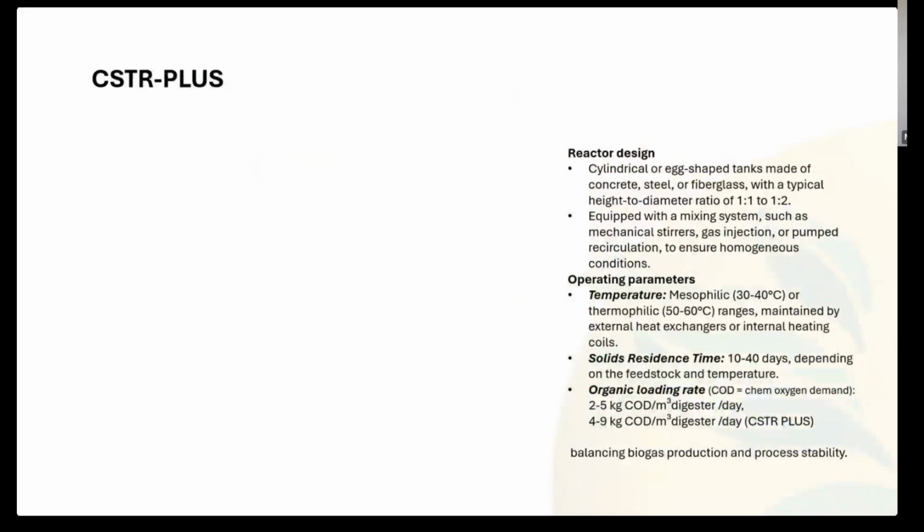At Organics, we offer, in addition to traditional CSTR design, CSTR Plus, where we add features to increase the digestion efficiency and the organic loading rate. Mixing systems like mechanical, gas injection, or pump recirculation are available for all those applications. Temperatures could be mesophilic or thermophilic, maintained by external heat exchangers or internal heating coils. Solids residence times, depending on the concentration of the feedstock, are between 10 to 40 days.